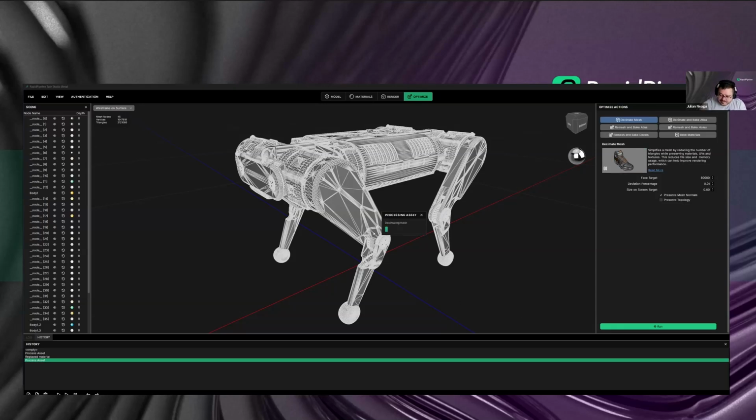As it's a large file, you can see it's processing at the moment, and we get the output. Two additional things to decimation: it actually has the option to preserve topology, which by default is off. This works pretty well if you don't decimate a lot, but if you want to decimate a really high amount, we recommend turning this off because it's just a constraint on the decimation actually. And having preserve mesh normals on is something we recommend. It's also on by default.